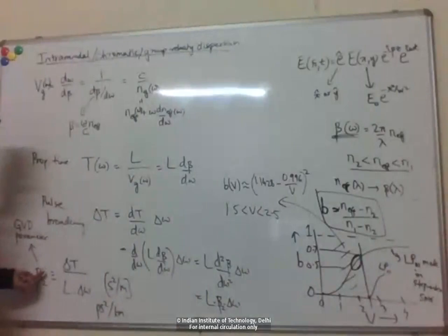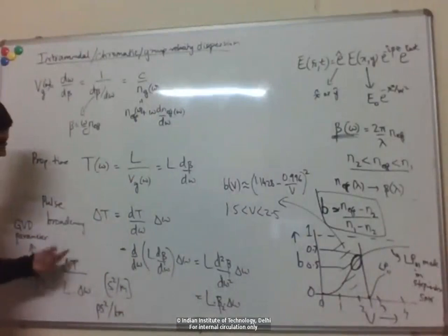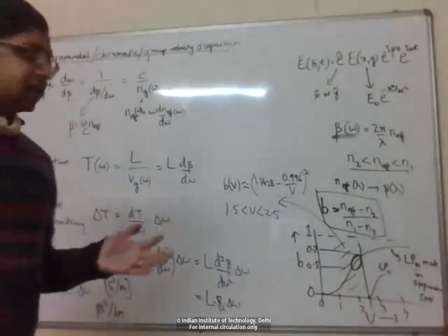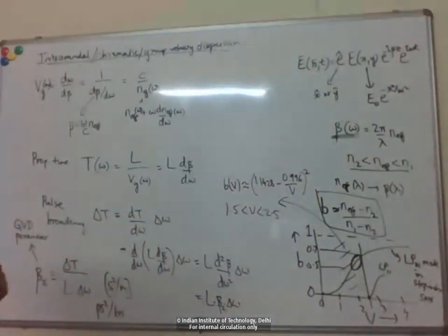So this will be some number corresponding to the fiber we are using, and so you can see that the broadening scales with length, just like in the intermodal case, but also with the bandwidth. In the intermodal case, the bandwidth didn't come into the picture, because we were just talking about spatial units. So this is basically in frequency units.